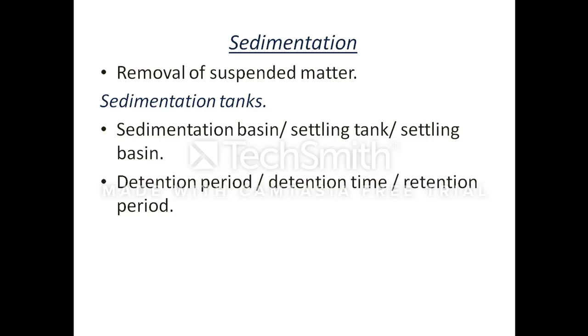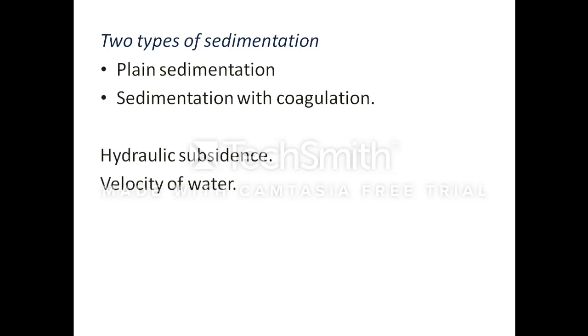As I told you, sedimentation is classified as plain sedimentation and sedimentation with coagulation. In plain sedimentation, the particles are removed by gravitational force. Plain sedimentation is the first process that is done, that is, a preliminary process. In sedimentation with coagulation, the fine particles are removed, that is the particles that are not removed by plain sedimentation.